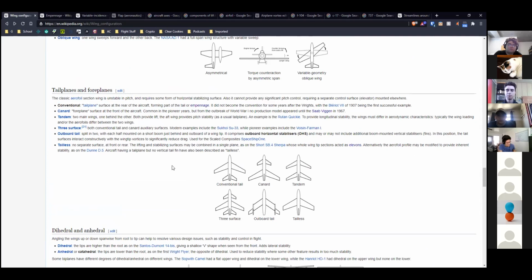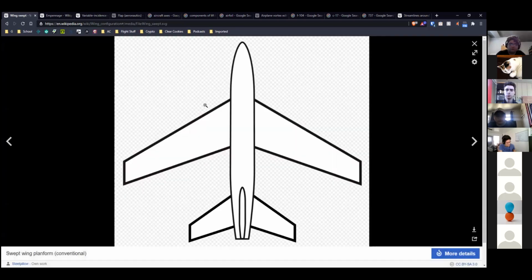I feel like now would be a good time to mention this, but for conventional aircraft, the place that you generally want the center of mass to fall in relation to the wing is around a quarter of the chord back from the leading edge root to the trailing edge root. Well, not the root exactly.